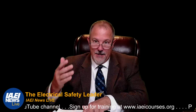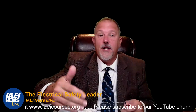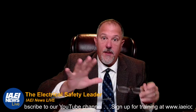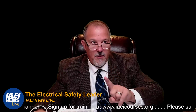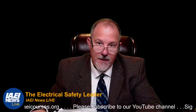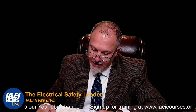See, you've got to follow manufacturer's instructions and guidelines. Fall back on the NEMA guidelines too, but think about the manufacturer-specific cable tray, because they might have specific requirements for their cable tray. They know how it's constructed. You can use the NEMA guidelines, which are a good document because all the manufacturers are contributing to that, making sure that it suits their installation. But you might be able to do something a little better or custom pertaining to a specific manufacturer.